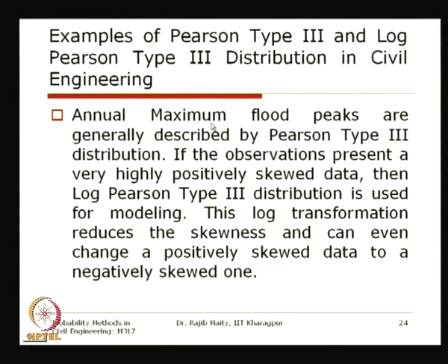In a year, from the data we have, we pick up the maximum values, and when we model only those peaks, it is observed that the Pearson type 3 distribution is very important, particularly for frequency analysis, that is, its return period, which is important for example to design a reservoir or dam.